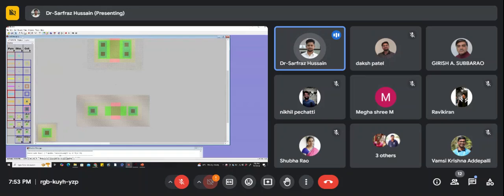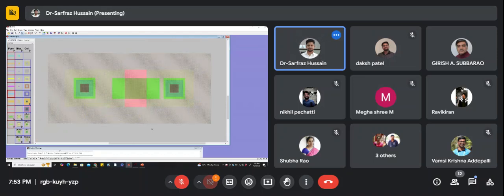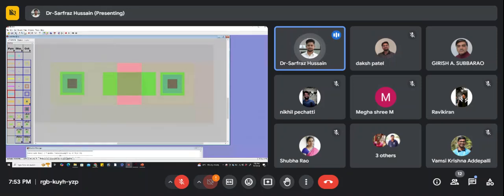Now for the NMOS side, again, you need to zoom into this. It's better if you zoom in, so then only you can make a good connection. Otherwise, there will be some errors. So let us connect here. Let's bring this one a little bit nearer. After we bring this one nearer, let us connect it: select, right click, connect.